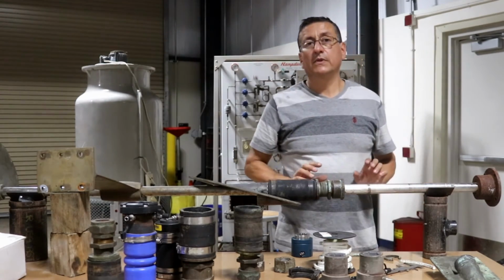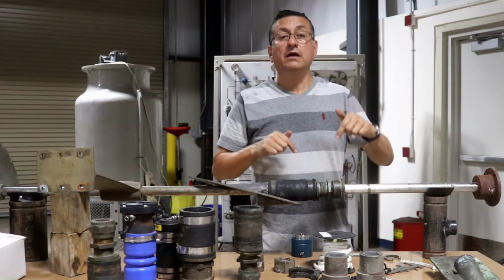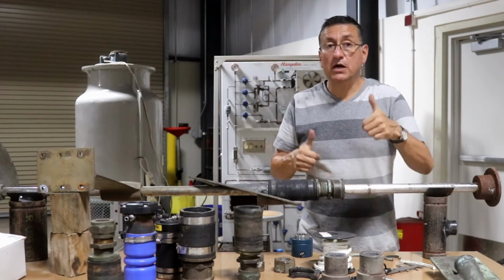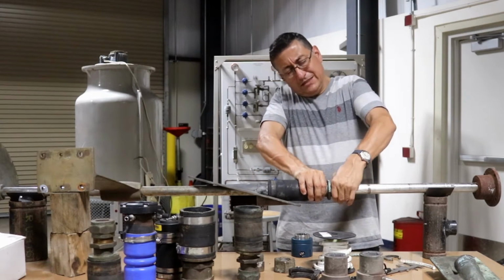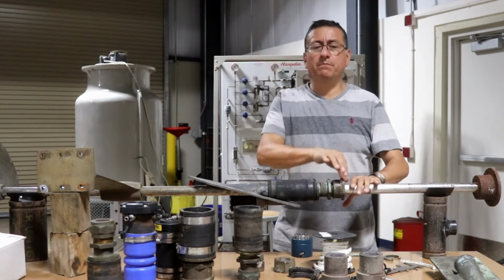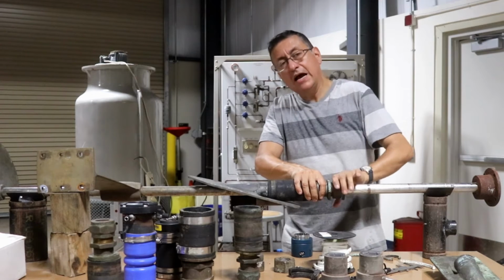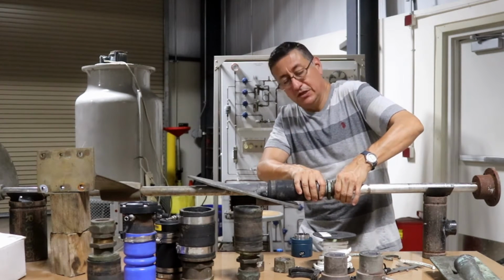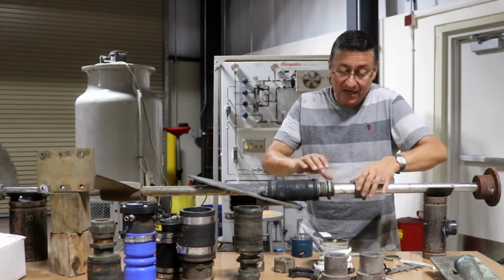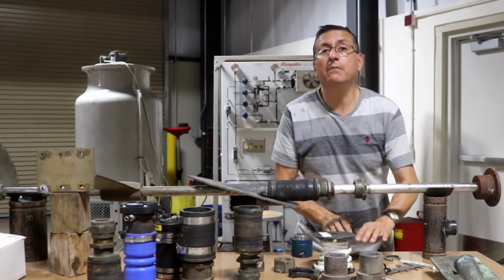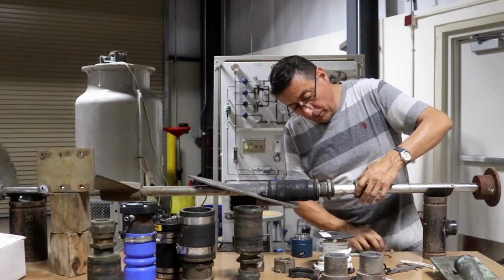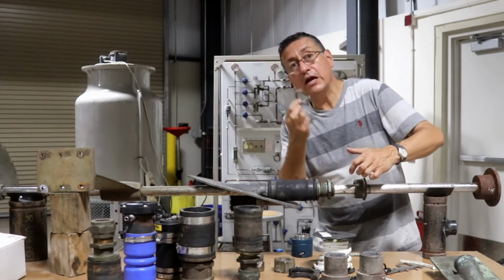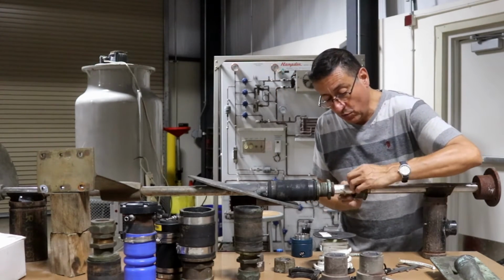Right now, 2 people inside verify that the bilge pumps are working properly, and you loosen the system with the pipe wrench. As soon as you loosen the system, you separate the nut and the water enters, but the bilge pumps start to work. With the screwdrivers, you remove the old seals and you introduce the new ones.